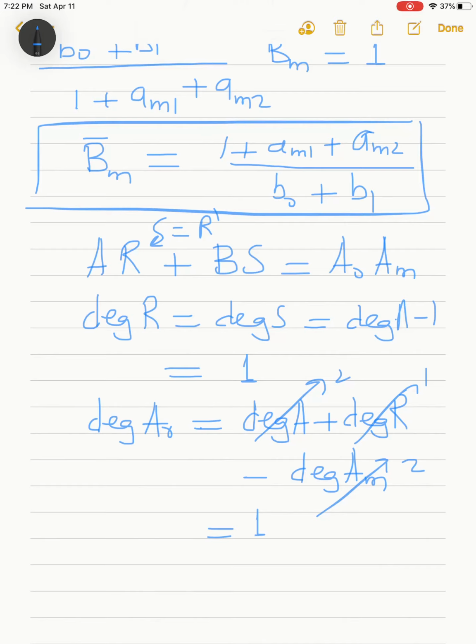Now one simple choice, let's write in terms of Q, is to just take the observer polynomial equal to Q, which means that we put the root at the origin. The effect of that, first of all, since the roots of A node will appear in the closed loop poles of the system, is that this is a fast pole that will not affect the dynamics of the overall system, because the dominant poles will then be those of AM. So this is from the transient response point of view.